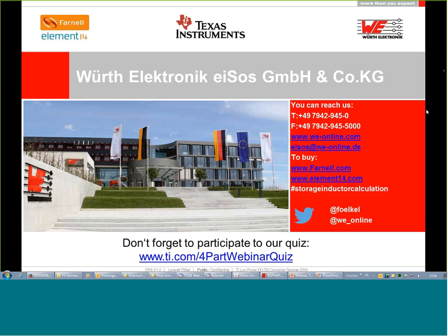On the output, if you want to filter the buck converter, it depends which frequencies you want to filter. You have to look with a spectrum analyzer, and if you still have some high frequency noise, which is maybe not coming from your DC-DC converter but from the input already and just passes through, then yes, you can make a simple LC filter using a chip bead ferrite and a ceramic capacitor, low ESR, low ESL as well. Capacitor before or after the ferrite? After the ferrite, LC.